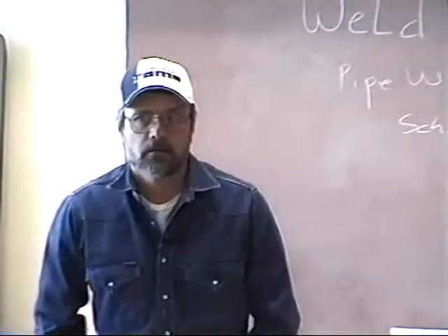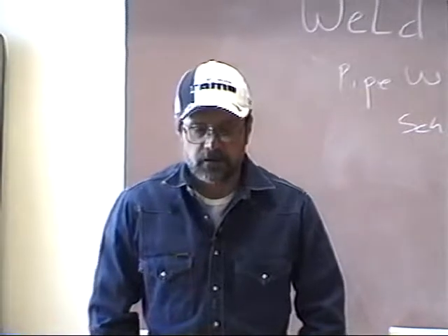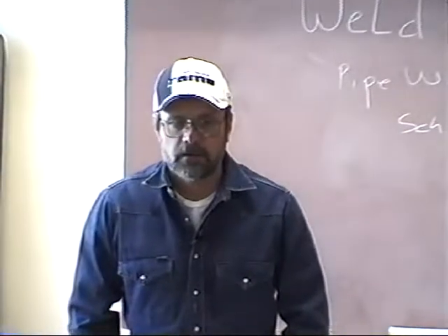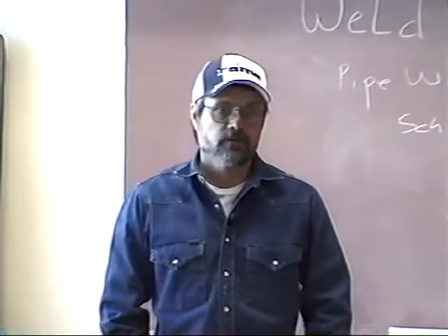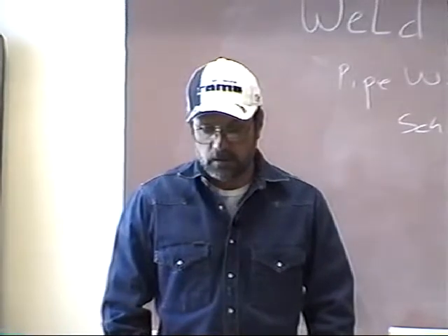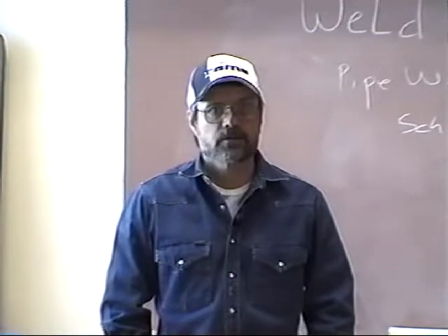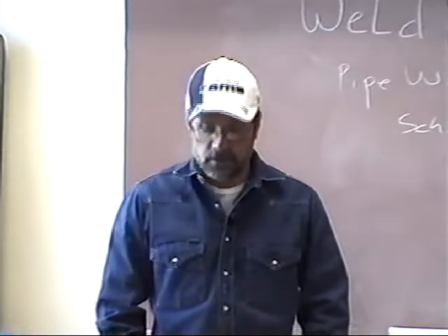heat. And by now, you should have a fair idea of how to evaluate whether or not you have enough amperage and if the volatility of the puddle is sufficient for what it is you want to weld. Of course, in the flat and horizontal positions, you can weld at higher amperages than you can in the vertical up and overhead positions. So the advice here is simply to go ahead and make a practice weld prior to starting any type of production welding.